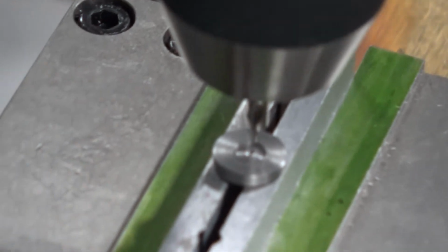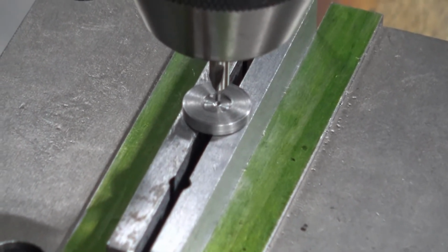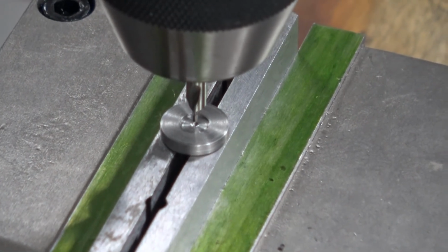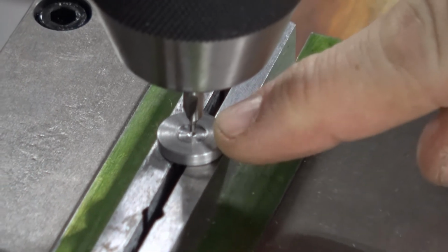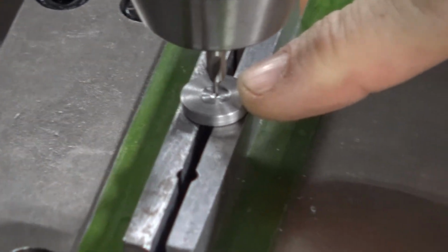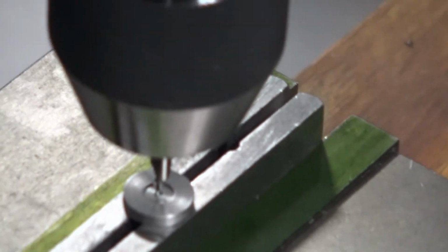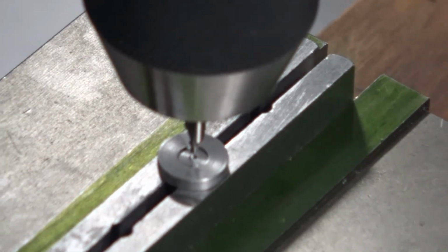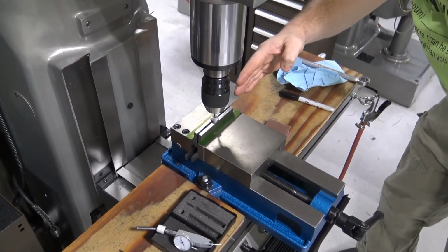Because visually I would like to line it up as best as my sight can see, right? We center drilled the center of that shaft to relieve for my 1/4 inch counterbore. So I've got it centered up well enough at this point that now I can switch over to my dial indicator. And I want to center that up both in this direction and in the front to back direction, okay?